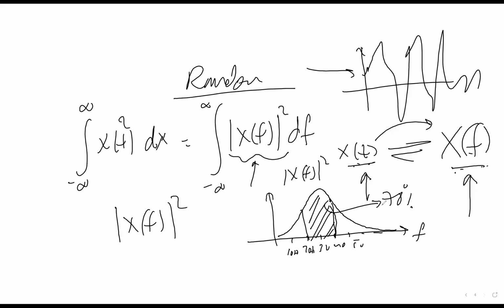So it gives you such important information: how the energy of the signal is distributed over frequency. This is very important in telecommunication and also in power systems. For example, when they try to recognize where a fault happened in the power system, we can usually track it by taking the Fourier transform of the signal, the frequency domain, and looking at the harmonics of the signal. We can determine with some accuracy, of course not 100%, where the fault should be and where it happened.